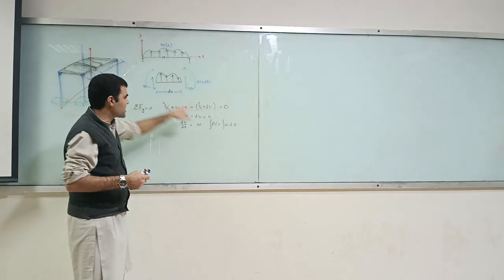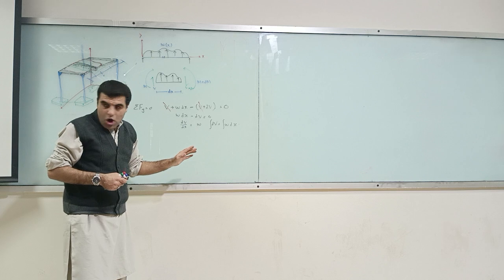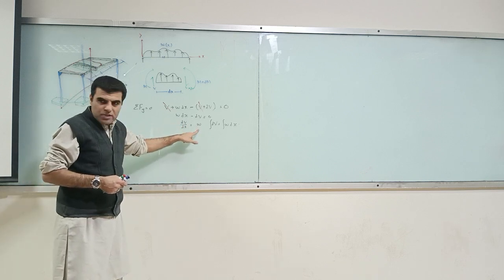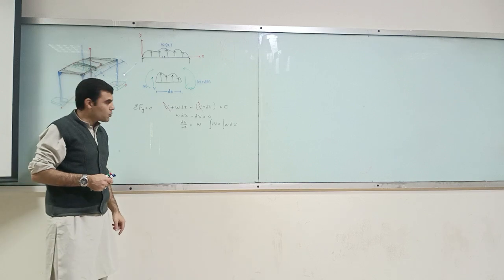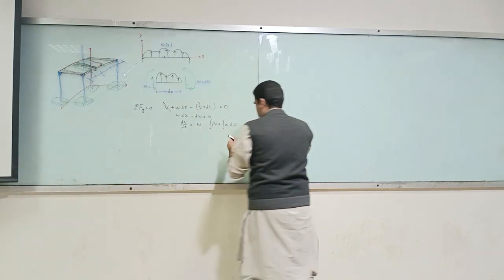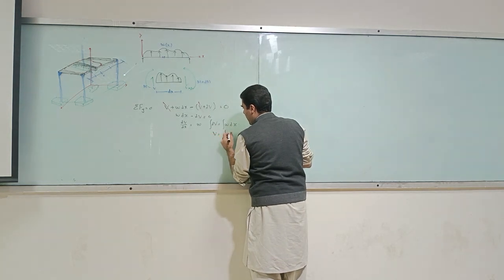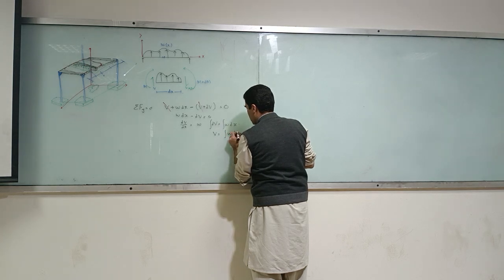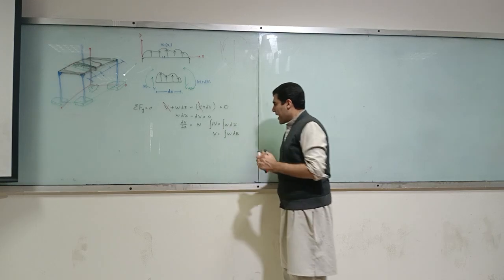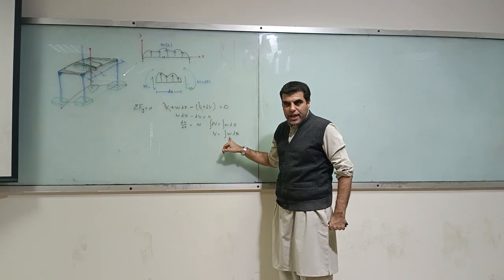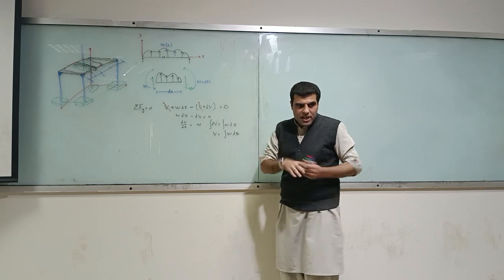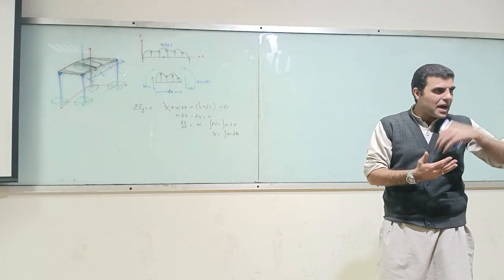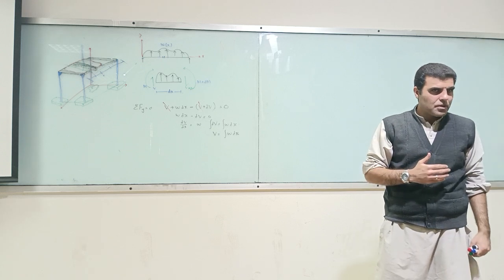The applied load is W dx. Or in other words, W, the applied load, is equal to the first differential with respect to x of shear. That's what this is saying. So V is equal to the integral of W dx, and if my W is constant, then my shear would be linear, and so on and so forth. So that's what this is telling me. That's my aim, to find the relation between my applied loads, the shears, and the moments. Do you understand my point?